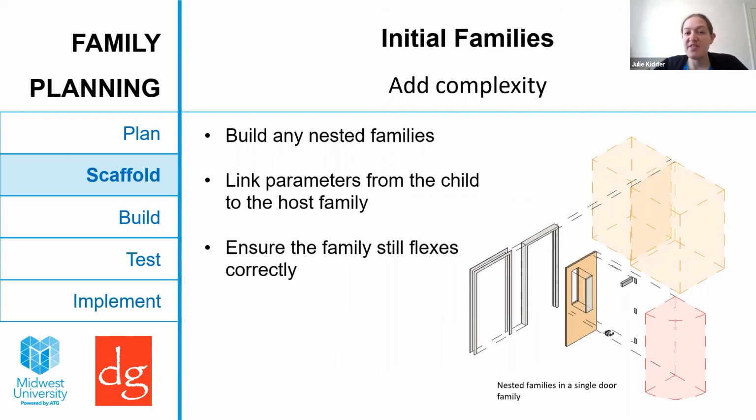How do you organize nested family types that appear in the parameters? I don't use different categories to limit the choice a user has, because that causes problems with visibility in templates. That was our problem with the clearances in our old door family. They were generic models, and if you couldn't easily control those independently, it didn't work the way users would expect.